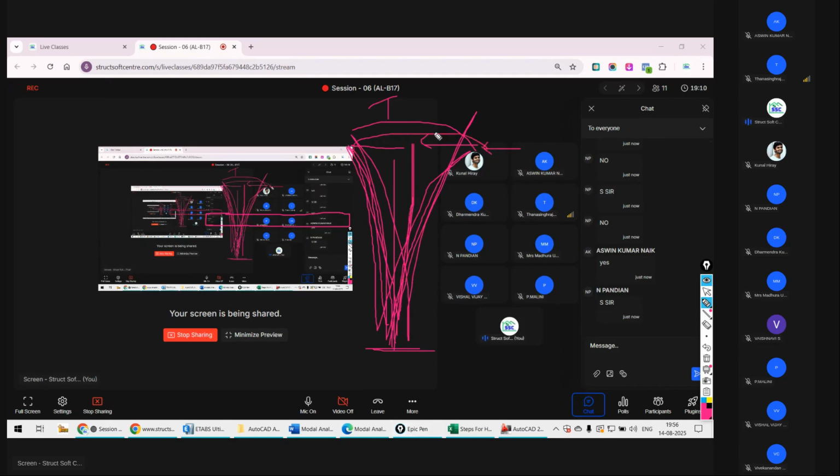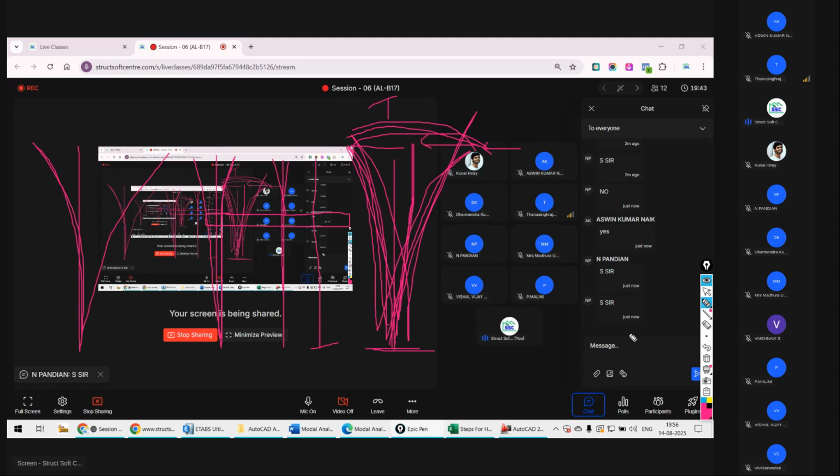And by this movement it is going to dissipate that energy. The energy that is stored, with the movement, what happens to it? The energy is dissipated. So initially you will find that this is going to oscillate in this way. After a few seconds, the movement will remain up to this much. Then after that the movement is going to become this much, and finally it comes to its static condition. That is nothing but the energy dissipation, and that energy dissipation is nothing but your damping property. Got it?